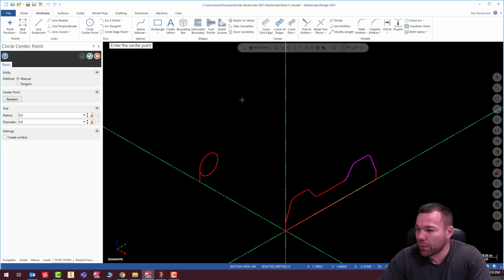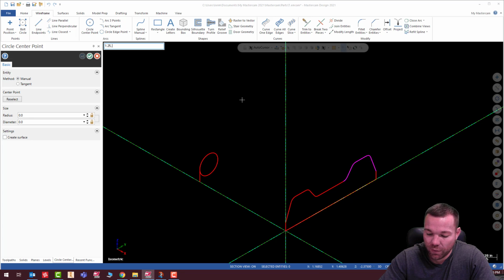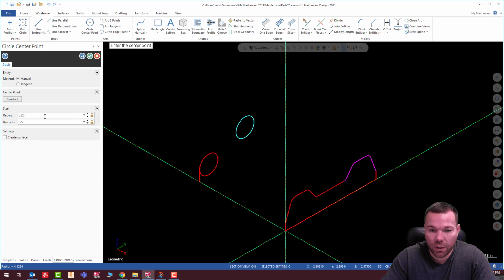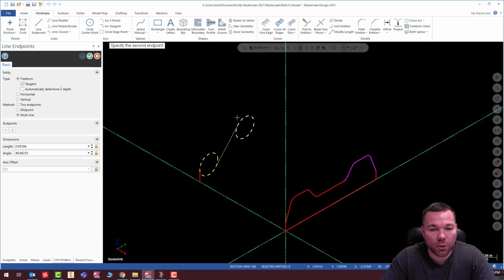So we know that this is 2.5, so the x-axis is going to be 1.25 because it's centered, comma, and 0.95 minus 0.25, which is just going to give us 0.7, enter, and our radius is 0.25, enter. And I'm going to check that and draw a tangent. Sometimes you can whirly bird that into there. All right, so there we go.